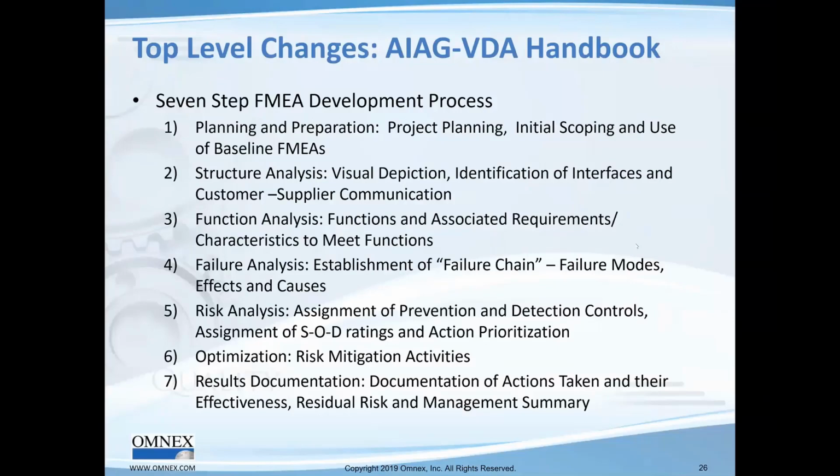In the next step of function analysis, we also very much today, we're getting better and better, in terms of doing FMEAs. You really should also do an interface matrix. Both of these tools are there in the AIAG VDA handbook as optional tools to use. Then in step 3, you look at the functions and requirements at the focus level, higher level, and lower level. Now, I've said this so many times, okay? And in the process FMEA, you really are looking at characteristics at the focus level.